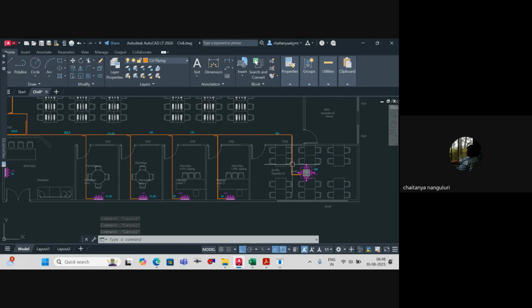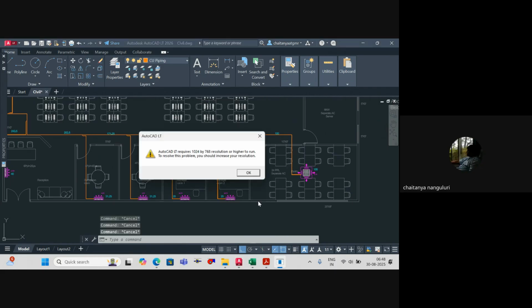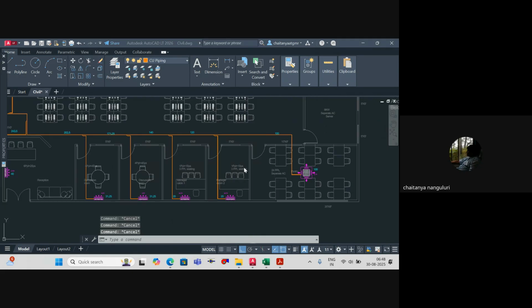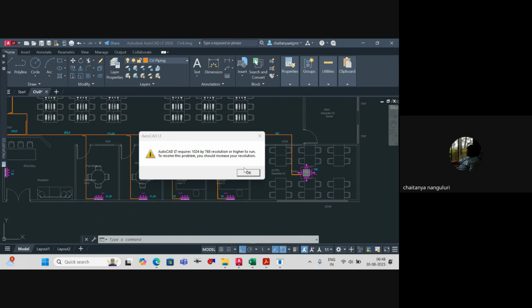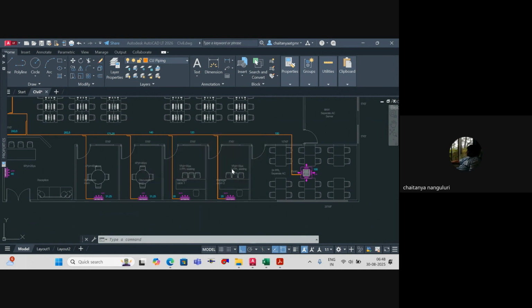Understood? So I have a sheet. Generally for a VRF system, a consultant or anyone will not do the pipe sizing. Of course, you require the pipe sizing to calculate the approximate sizes anyway. Generally, this will be done by the OEM, like manufacturers will do the pipe sizing. All you have to give is pipe routing and indoor capacities.